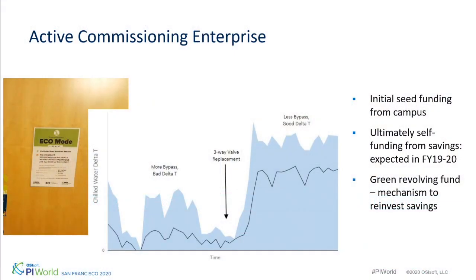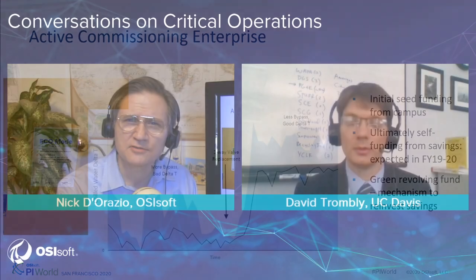Okay, right. What were the interfaces that you needed to use to get those two sets of information together? Was that both from the same control system, or different control systems? So the plant control system is a Wonderware system, and we're currently using the RDBMS interface for that. We're not using the new connector for that particular Wonderware control system, but for a different one. We've collaborated extensively with OSIsoft to use the new Wonderware connector, the connector for Wonderware Historian. That's for our water and gas SCADA system. Eventually we'll roll that over and use it for our central heating and cooling plant SCADA system.